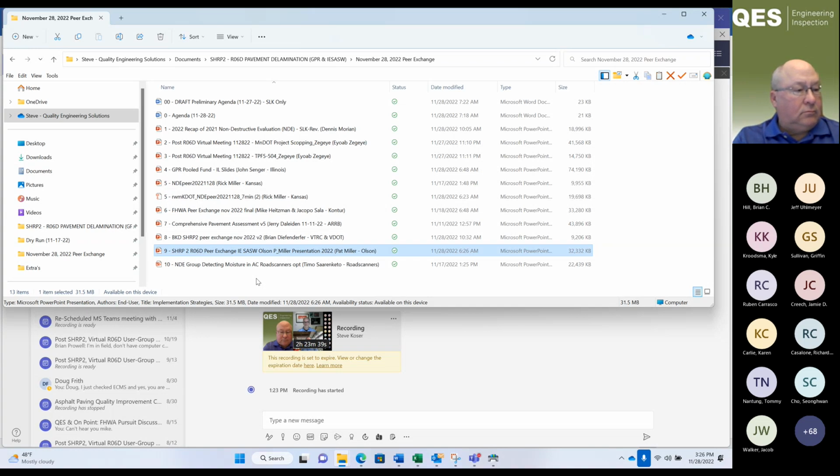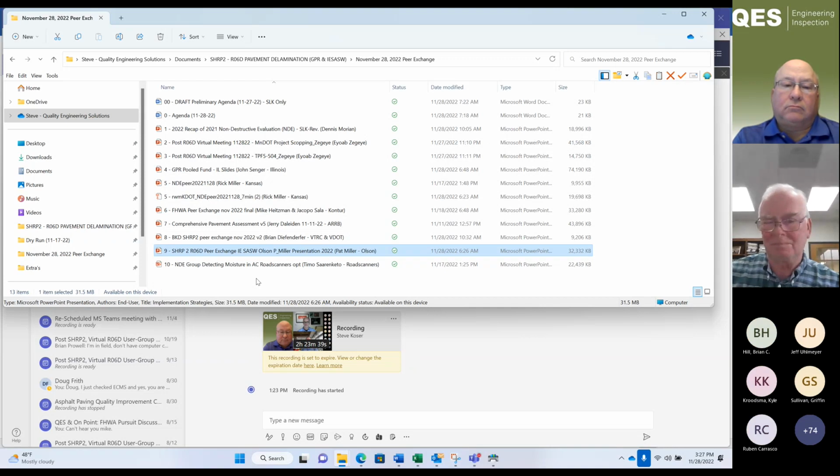Regarding the second question, the SW system works well at the full range of temperatures we've tested so far, which included very hot pavements in New Mexico. So the SW doesn't have any limitation on temperatures. It's the impact echo method that does not work very well when it comes to hot asphalt. So that's why on asphalt pavements, we recommend doing the SASW testing.